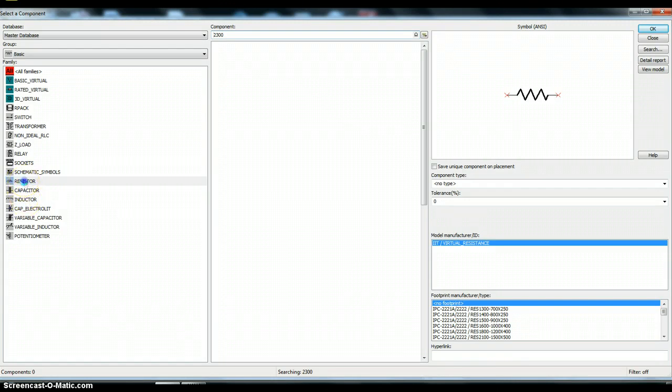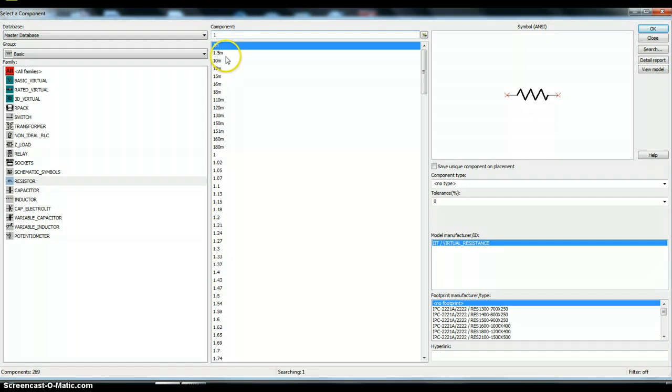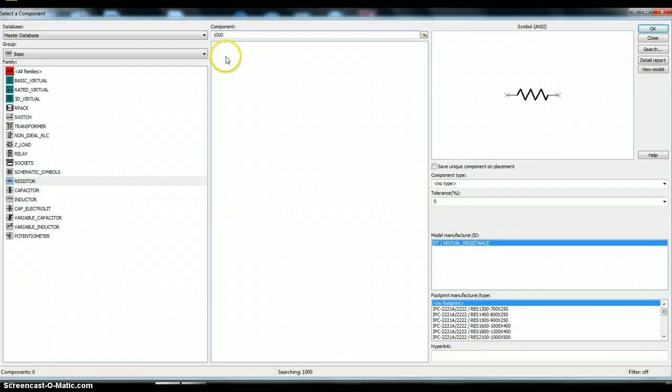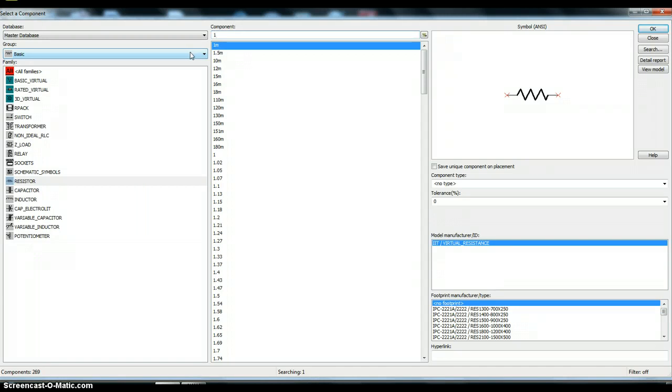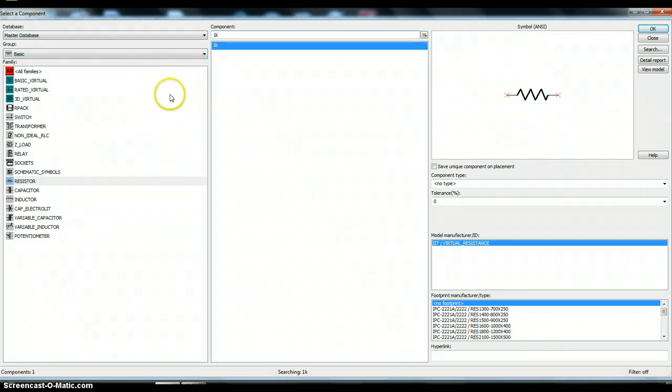In the case of resistors, with this particular version, you actually set the value up here to whatever you want. So for example, if I wanted a 1K resistor, I can enter that as 1,000, or alternately, I can enter it as simply 1 and K. Now, I'm not going to open that up yet. I'm just showing how to list the values.